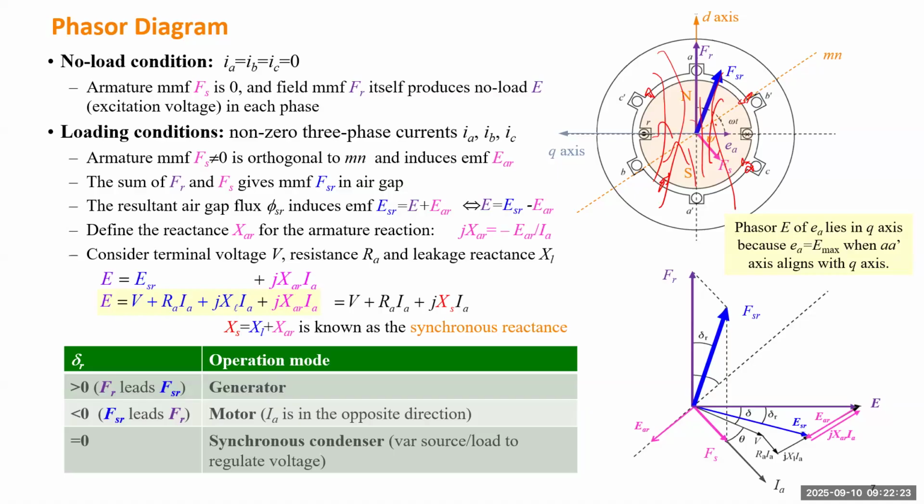But the flux depends on the material inside of this magnetic field. So if the inside of the stator is a fully magnetic material, the flux can be really large. But if the material is not magnetic, the flux can be smaller. Okay, so which means the flux in the air gap and the inside of a rotor can be very different. And for this case, it's simpler because the rotor has a round shape. When it revolves, even though the spatial position of the rotor relative to the stator is changing, the flux density doesn't change too much.